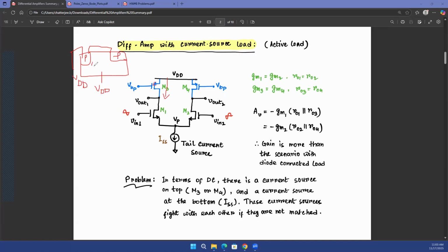So this is the source, and this is the drain of the PMOS, which is at a lower potential than VDD. That means the PN junction diodes, since the body of the PMOS is always an N-type semiconductor, are either zero biased or reverse biased. That means there is no additional power loss because of those diodes getting turned on. That is the reason why you would like to connect the source of the PMOS to VDD and the source of the NMOS to ground.